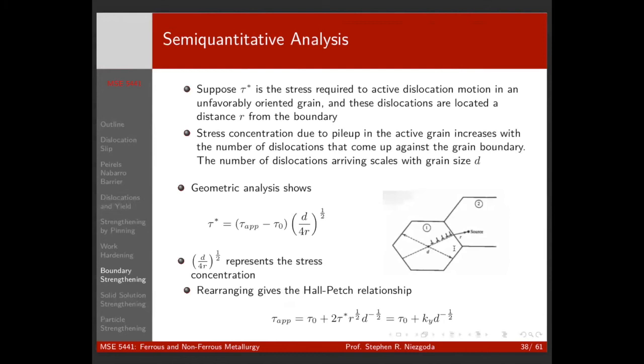We don't know what's going to happen, right? This is another really cool open area of research. Sometimes at the grain boundary, the dislocations go right through like it doesn't matter. Other times they pile up. Other times they get absorbed and disappear. Other times they rebound off. Sometimes you have debris left behind, where the slip systems are not well aligned between the two grains. You have one dislocation type that comes in, another dislocation type that comes out, and your grain boundary structure has been altered, right? Again, another really important fundamental area of research that we still don't quite understand.